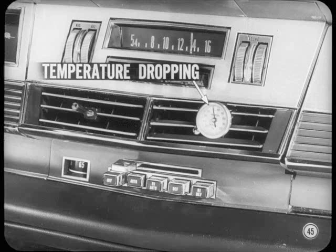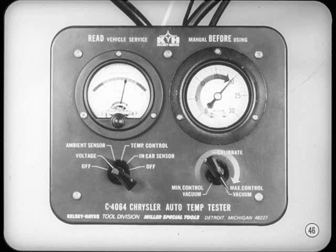You should be getting cool air from the air conditioning outlets and the air temperature should drop. That's because the tester vacuum dial, which is acting as a selector dial, is asking for less heat because of the low vacuum. To further check the auto push-button operation, slowly move the tester vacuum control dial from minimum vacuum